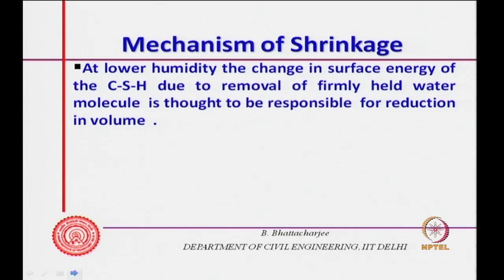At lower humidity, of course, the change in surface energy of the CSH due to removal of firmly held adsorbed water molecules is thought to be responsible for reduction of volume.